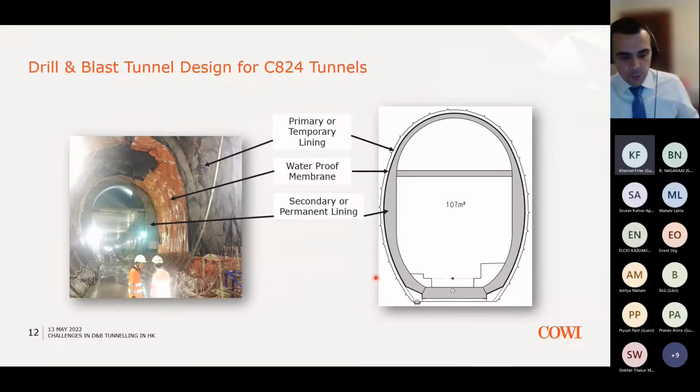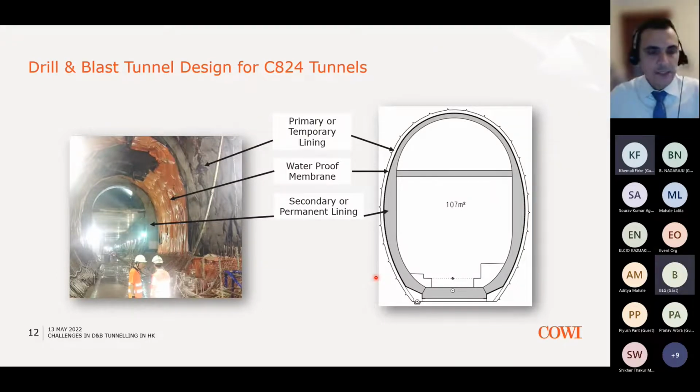For this project, the client indicated that they would want to have a permanent lining as well. For this to happen, obviously, you need the temporary lining to be installed first to provide a safe environment for the workers to work underground and install the permanent lining.